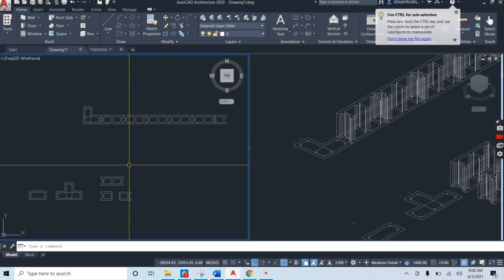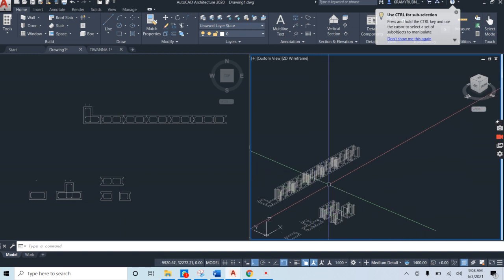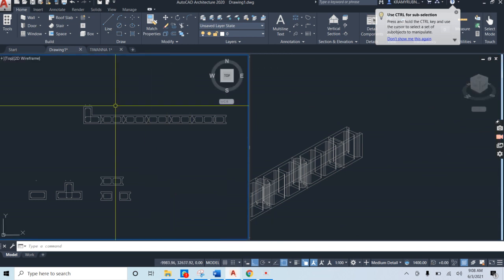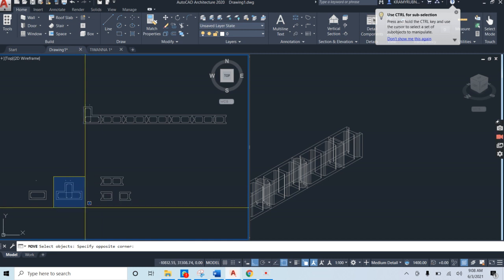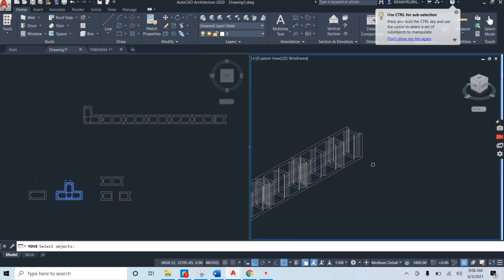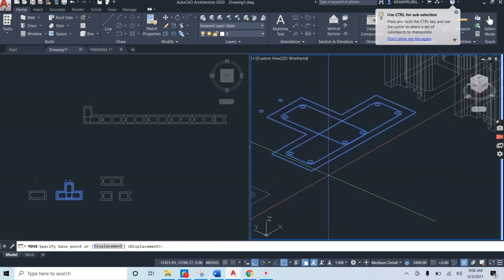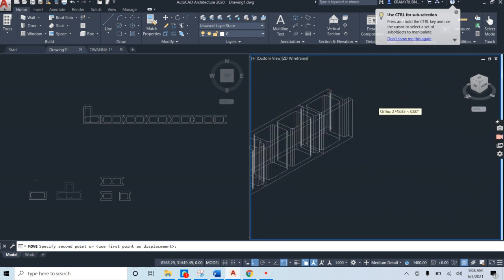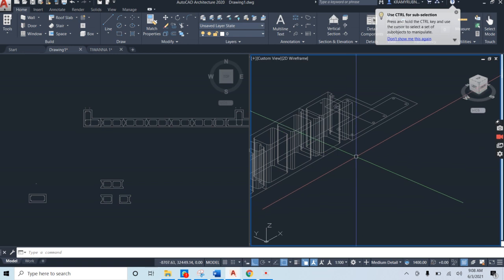Let us continue. Now at this other end, we're going to be placing our T stiffener. So let us go and move our stiffener, selecting everything on this side, ensuring that everything has been selected. Let's go over here and find it, enter. We're going to move it by holding it at this point and moving that point and placing it here. Now our stiffener is placed in our wall.